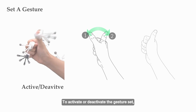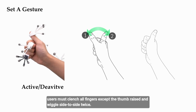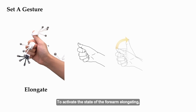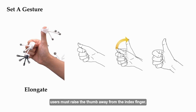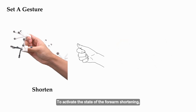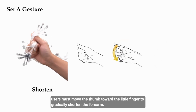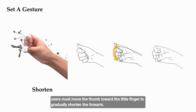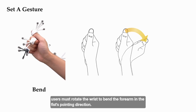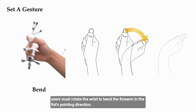To activate or deactivate the gesture set, users must clench all fingers except the thumb raised and wiggle side to side twice. To activate the state of the forearm elongating, users must raise the thumb away from the index finger. To activate the state of the forearm shortening, users must move the thumb toward the little finger to gradually shorten the forearm. To activate the state of the forearm bending, users must rotate the wrist to bend the forearm in the fist's pointing direction.